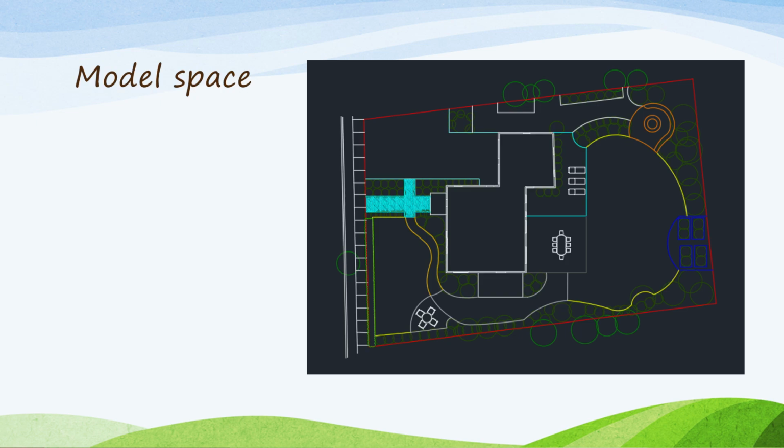In this space, we used various tools for drawing the design, such as the line, polyline, circle, arc, and hatch tool. Each of these tools were used for their own respective parts of the project. The polyline and line tool were used to draw straight segments on the project, such as the existing house or the property line. The difference between these two tools is if the object was drawn with the polyline tool and you select it, all the segments will be selected, whereas with the line tool, each segment can be separately manipulated.